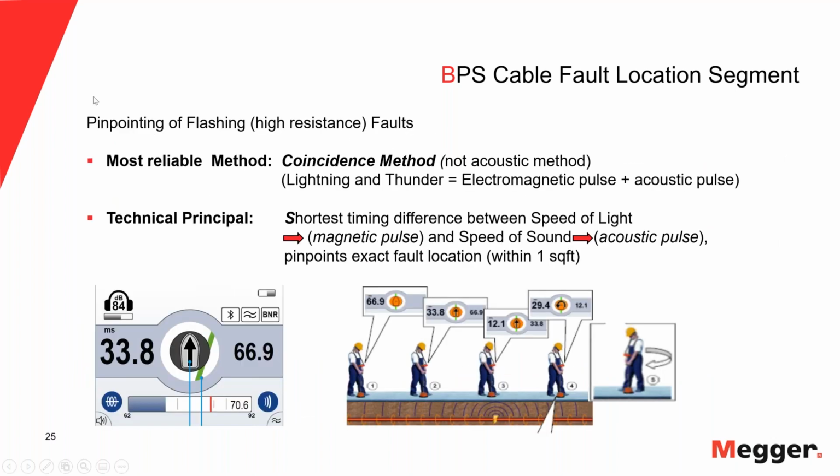Okay, so once we have established a pre-location distance, now we can do the pinpointing. And we do pinpointing clearly when this is a direct buried cable, because we need to know where to dig the hole. But even if we have cable in conduit, it is a very good practice to do a pinpoint, because it confirms the result of what the pre-location method did yield.